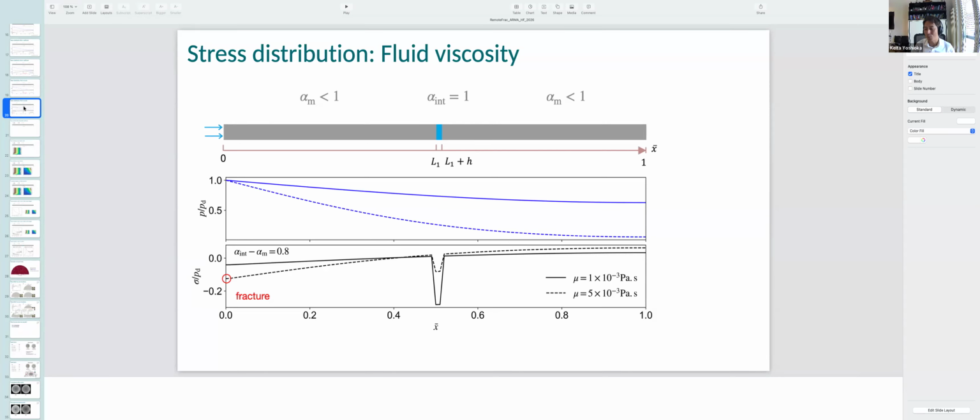if you have some weak interface away from the borehole, even though fracture will not initiate out of the borehole, the weak interface here, the Biot coefficient is high, or 1. And for high Biot coefficient, the fluid pressure impacts more at high Biot coefficient rock.